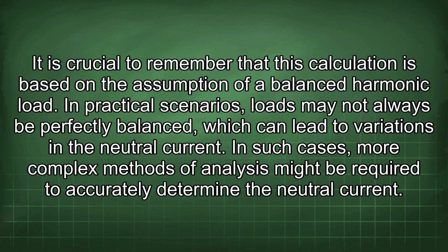It is crucial to remember that this calculation is based on the assumption of a balanced harmonic load. In practical scenarios, loads may not always be perfectly balanced, which can lead to variations in the neutral current. In such cases, more complex methods of analysis might be required to accurately determine the neutral current.